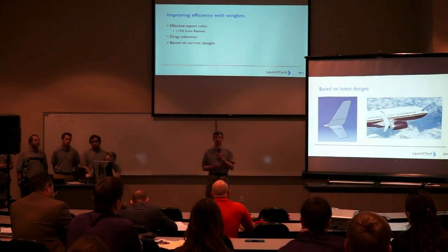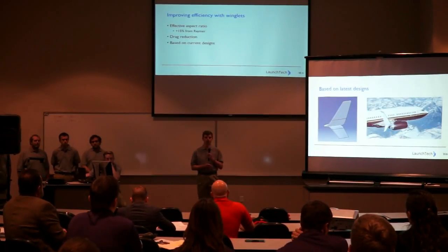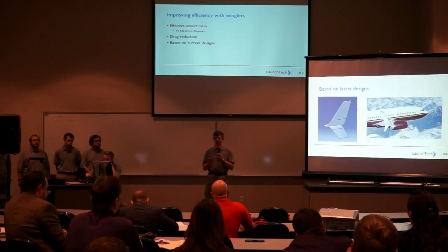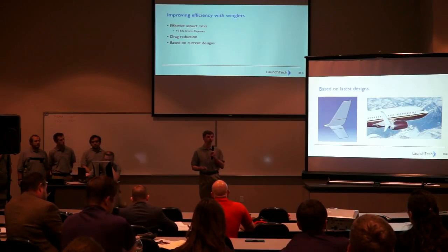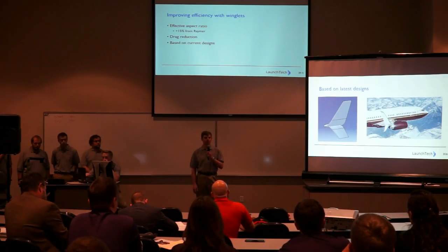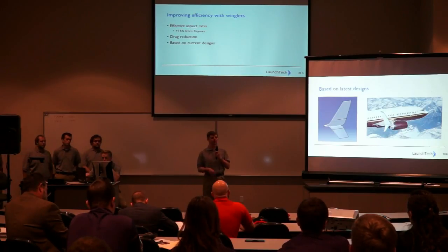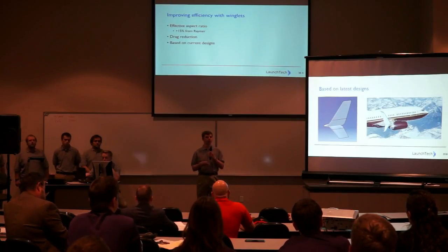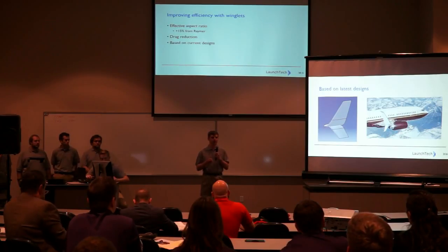Now for winglets, according to Raymer, winglets can increase our effective aspect ratio by up to 20%. We estimate that we can achieve 15% using winglets modeled after current designs. For example, on the secondary screen, the PT-1's winglet versus the Aviation Partners split scimitar winglet. This is a new winglet designed recently by Aviation Partners for 737s, and it increases the performance of the wing by reducing drag significantly versus a wing that does not have any winglets at all.